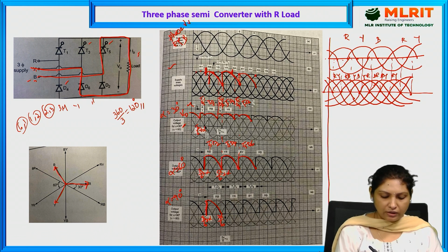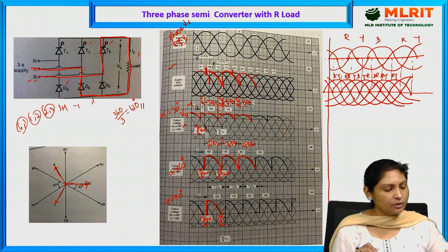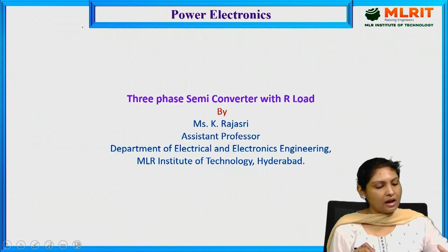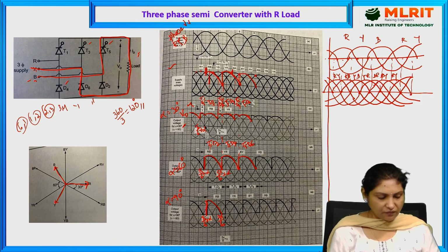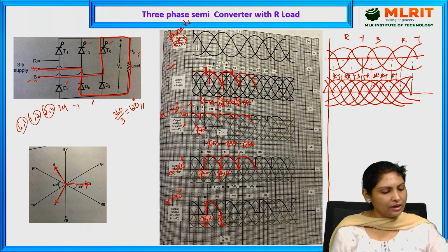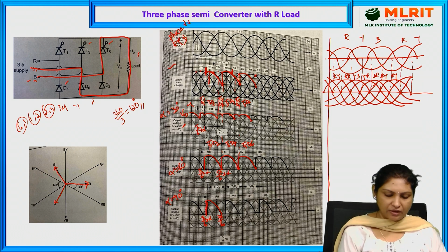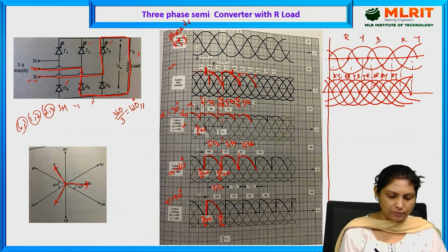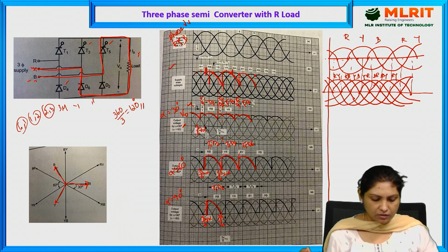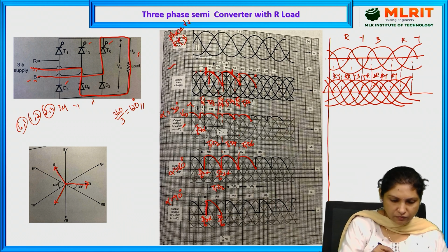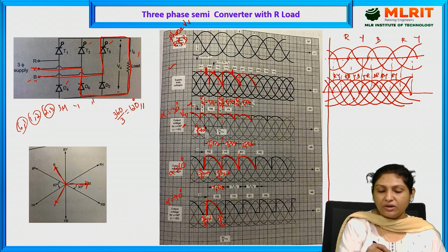Okay, we have got RB phase, and you know very well, because of RB phase, thyristor 1 as well as diode 2 will be active. So now what happens here? At this instant called 0 crossing, we have provided the triggering pulse, and now at this instant called 0 crossing, Y phase has appeared, and we are supposed to provide the triggering pulse at alpha equal to 90.